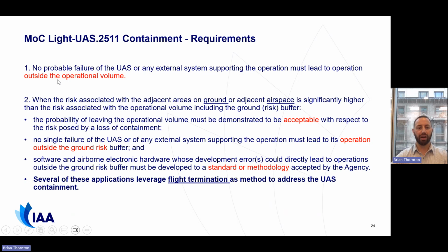Again, within the realm of MOC 2511 containment, point one: no probable failure of the UAS or any external system supporting the operation must lead to operation outside the operational volume. That's the key point. We want to keep our UAS within our operational volume that we have defined and measured and put into place before we conduct our operation.